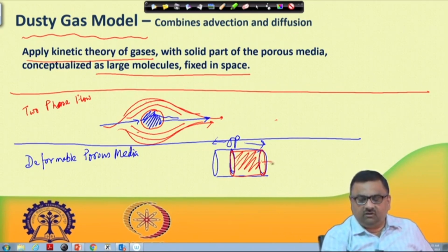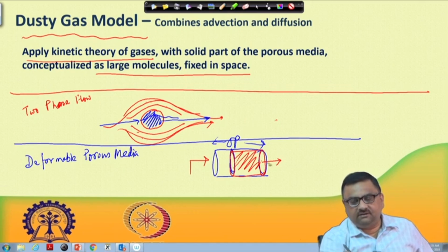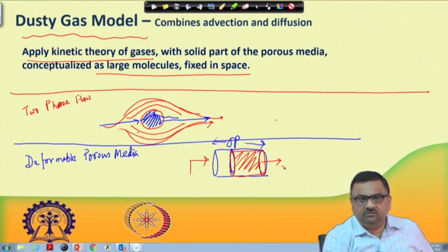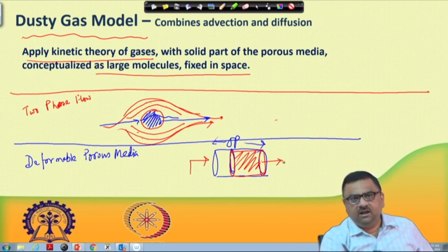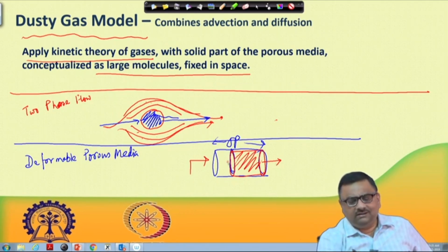Naturally, when we are talking about flow here, I am having a flow. There is some flow rate, so it is flowing, but at the same time this porous medium itself is getting squeezed. This part of the void space was also occupying some fluid, and that fluid is also coming out from the outlet. So with time, this porosity is decreasing, as one is squeezing this whole setup. In fact, this is not a new transport mechanism as such. This is again that same mass continuity we have to work with, only the porosity will change with time, and we have to look into that.